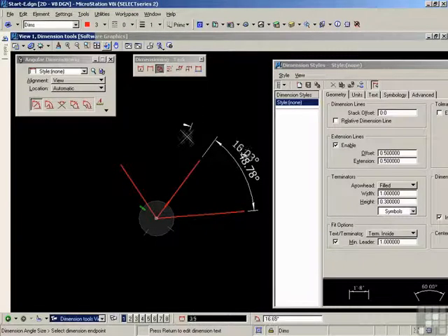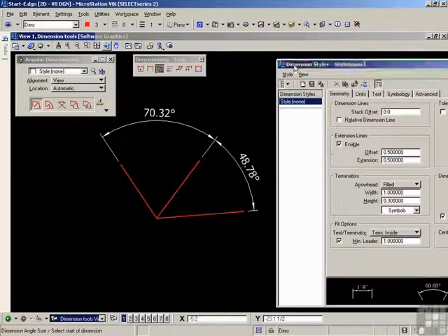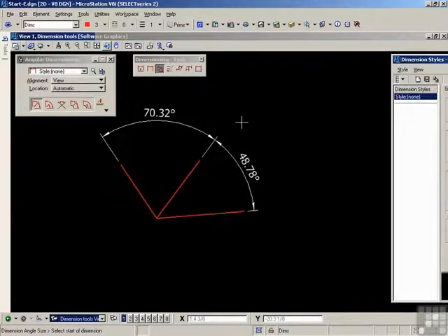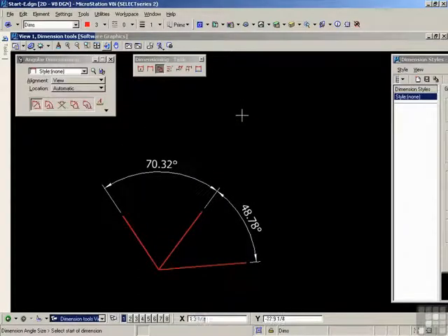And now if I drag this way, I can now immediately place the next dimension along. So this is a dimension string. Left click and snap to that line end, and right click to stop the tool. And there are my dimensions neatly in place. Let me move this down a little bit for more visibility. Now this is obviously really quite straightforward, provided you remember that you will need to select the center for the arc dimension line. Let's try the next tool.